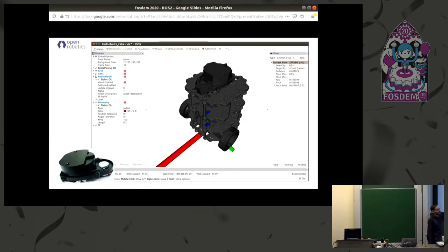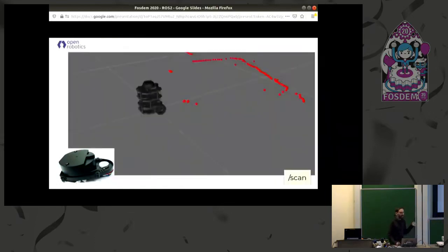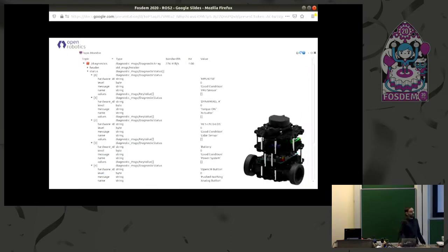There's no laser scan in there yet. These colored bars you see there are the axes for the reference frame of the robot, right? And what you can put inside RViz are those red points. These are the readings from the laser. With that, you are able to do something really powerful, which is to diagnose whether your system is working fine and how it's working.